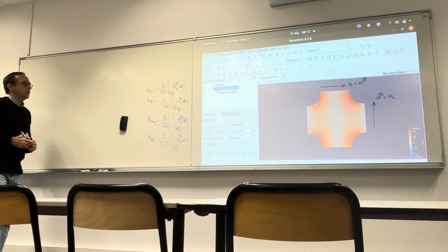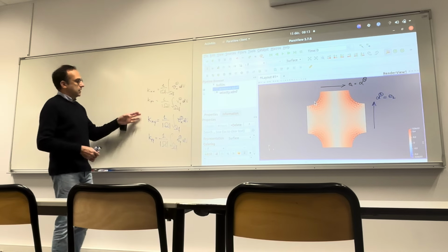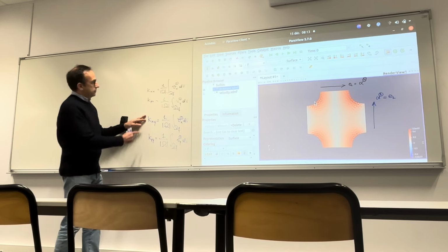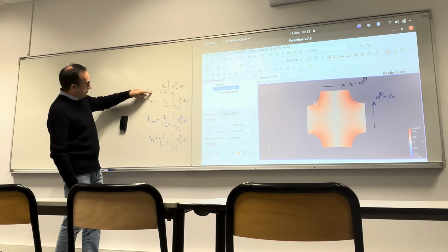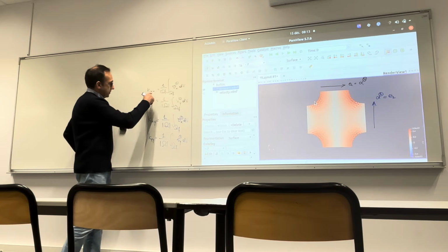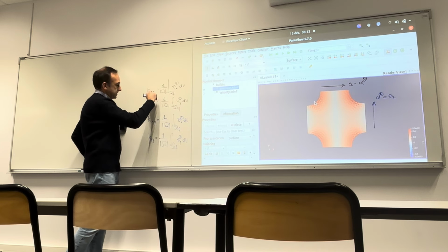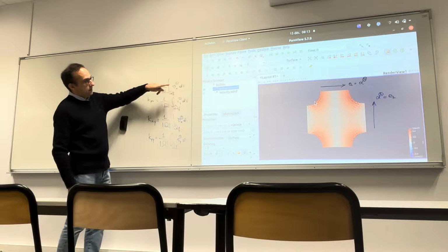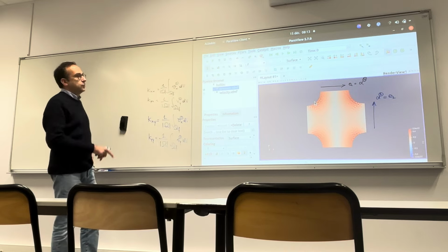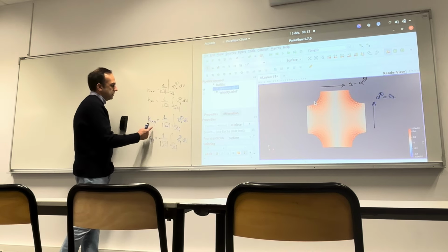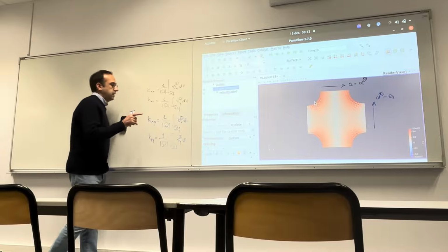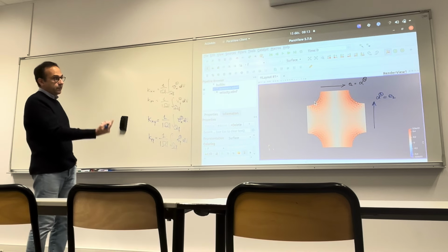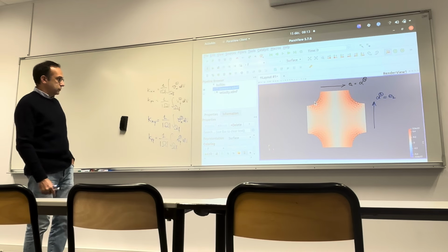Okay, and so with these definitions, essentially the Kx and Ky with first index, second index x will be the average of the velocity field induced by a horizontal unit gradient of pressure, and these ones with the last index y will be the average of the velocity field due to a unit gradient of pressure along the E2 direction.